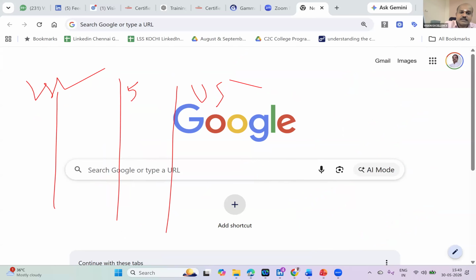Exactly. So I give another example to all of you. Right? I'm saying 50, 53, 47. Now tell me what this is, customer specification. Now what is the customer given target? 50. And what is the upper spec given by customer? 53. Lower spec given by the customer is 47. That means the tolerance is plus or minus 3 microns.